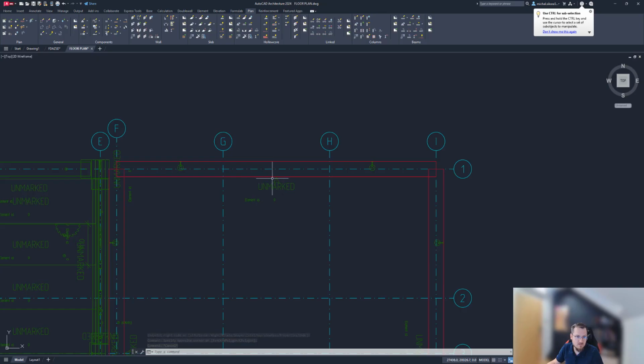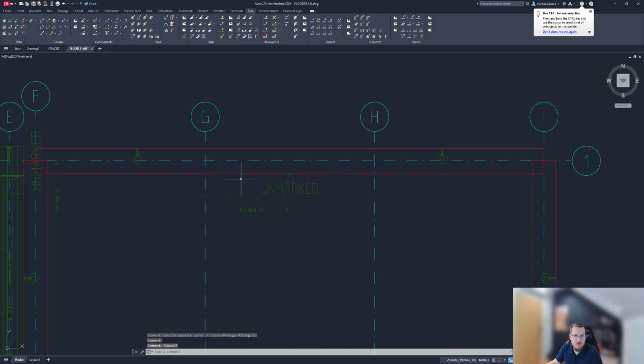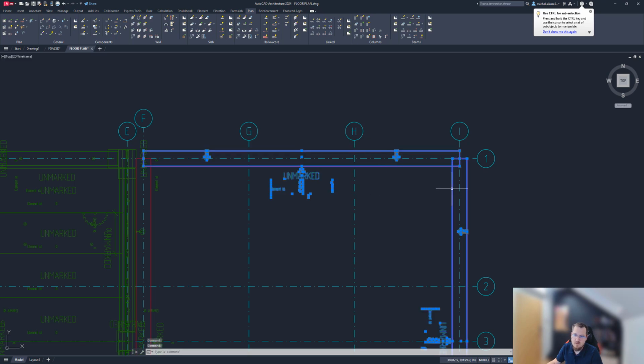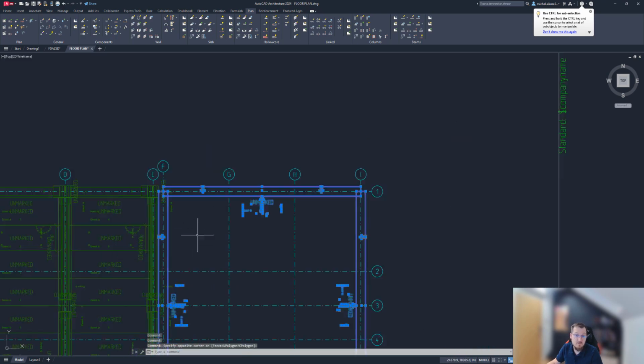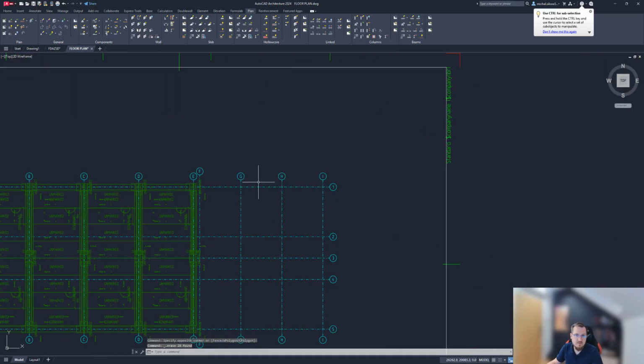Oh, and I've noticed that I've input the panels incorrectly. So sorry, I'm going to quickly delete that. Some of you probably noticed, but the bracing anchors are on the outside of the walls. That means that our inner panels are on the outside. That's very often something that I forget. That's the directionality of your inputs in CAD, and honestly, it's much simpler to just start over.